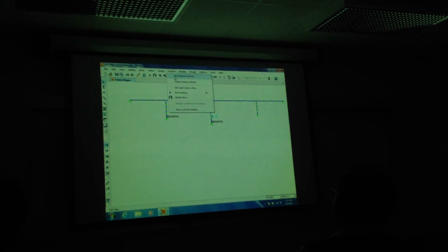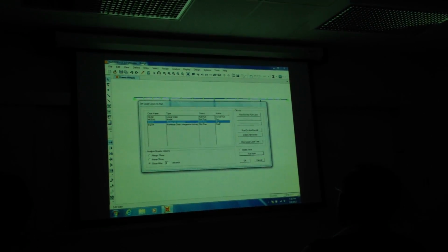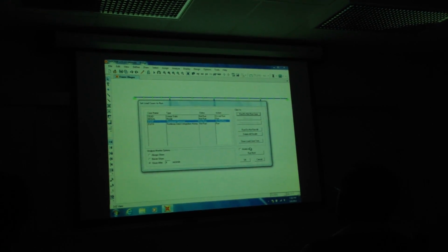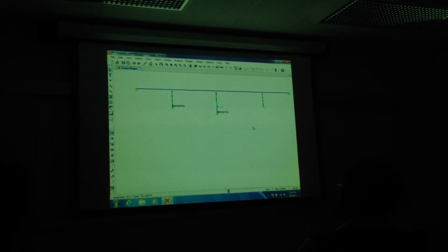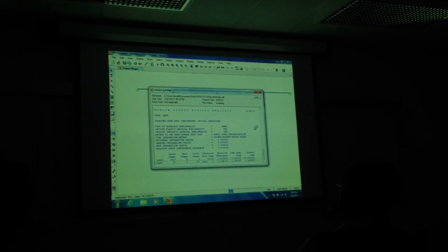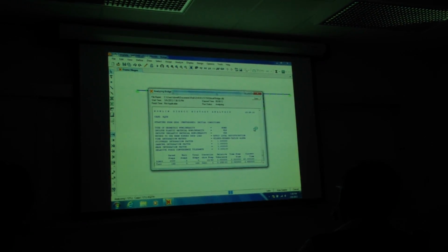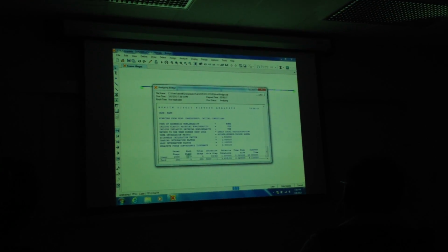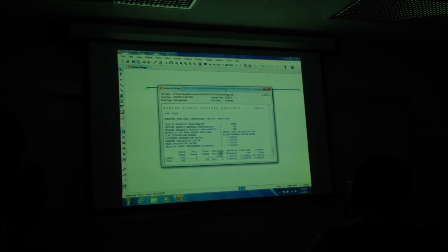Run analysis. I have to be careful because it's going to run again. I don't need the response spectrum to run, so I'll say don't run that one, because then we'll accidentally click that. Okay, here we go. So now it's going to run, solving the problem every 0.02 of a second, and if something goes nonlinear, it'll iterate until it balances all the forces, and then keep going. And sum all the incremental results, we get the total results. So it's running. There are 2,000 steps. It's at 190, 200 right now. So it's 1/10 away. It's saying it's converged. It's iterating and continuing.